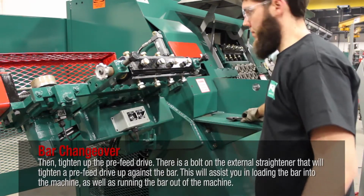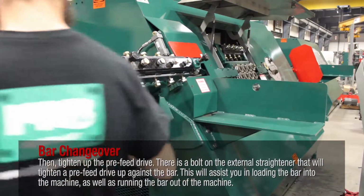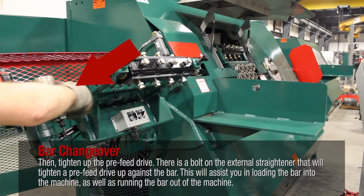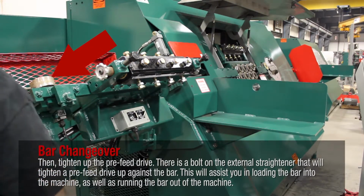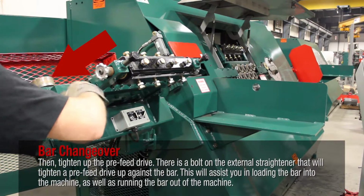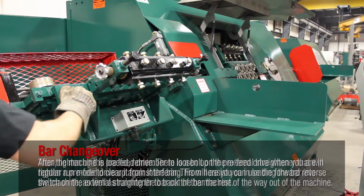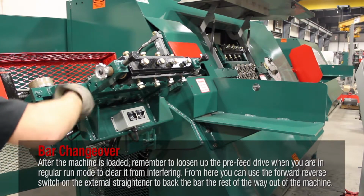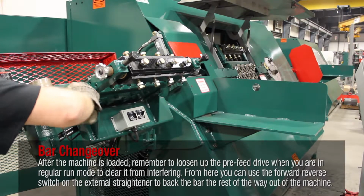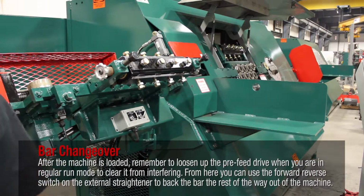Then tighten up the pre-feed drive. There is a bolt on the external straightener that will tighten a pre-feed drive up against the bar. This will assist you in loading the bar into the machine, as well as running the bar out of the machine. After the machine is loaded, remember to loosen up the pre-feed drive when you are in regular run mode to clear it from interfering.